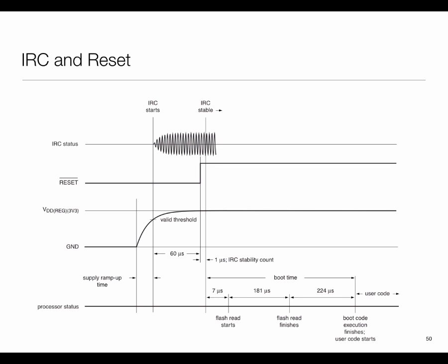And in this particular case, you could see that the whole boot up time of this particular thing running some lightweight operating system can add up to a good fraction of a millisecond. So by the time you're done, a lot of time is wasted. This becomes a bottleneck, if you may, in rapidly duty cycling a processor.